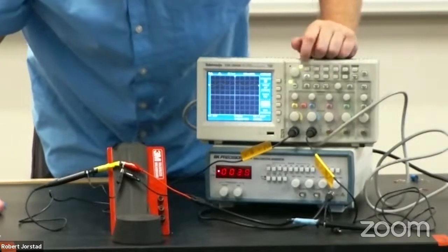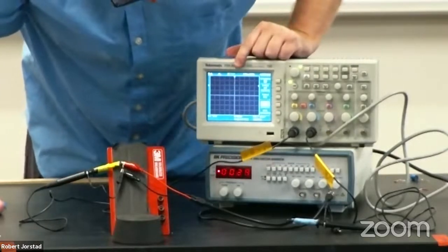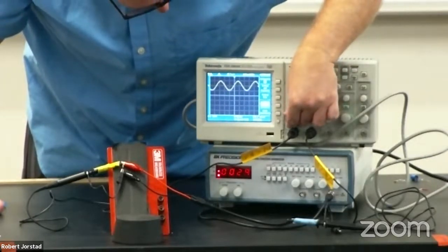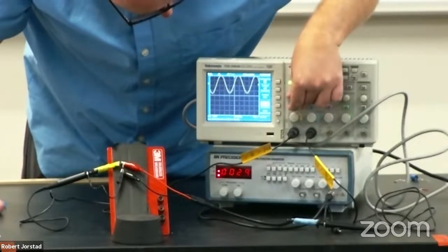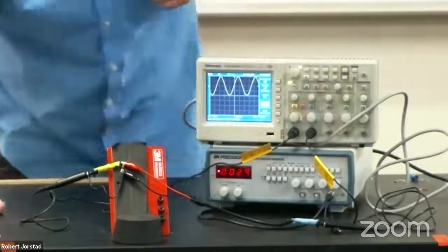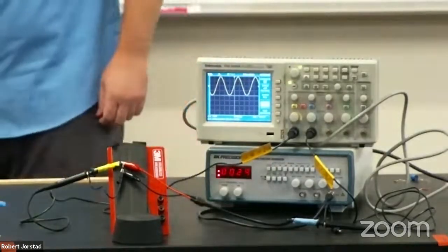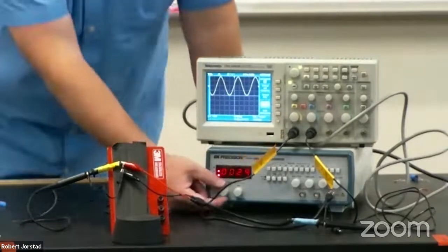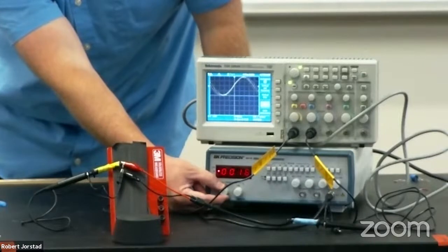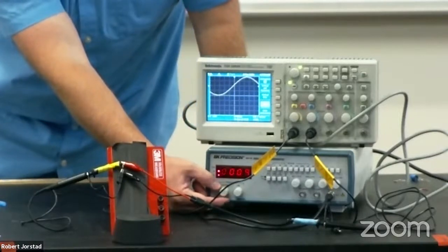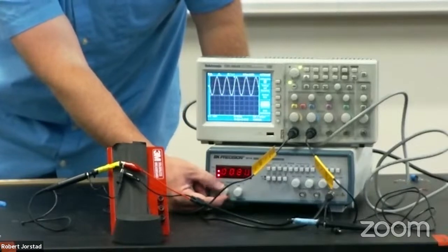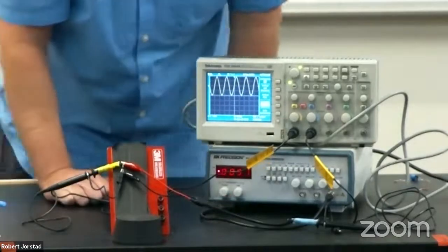And if I hit this button auto range, it'll just take a second to respond. And maybe I'll just manually range here. Now you can see there's a sine wave here. All right. And what I'm going to do is gently adjust the frequency. And notice when I lower the frequency, we see fewer waves on a screen. When I increase the frequency, you start to see a bunch of waves on the screen.